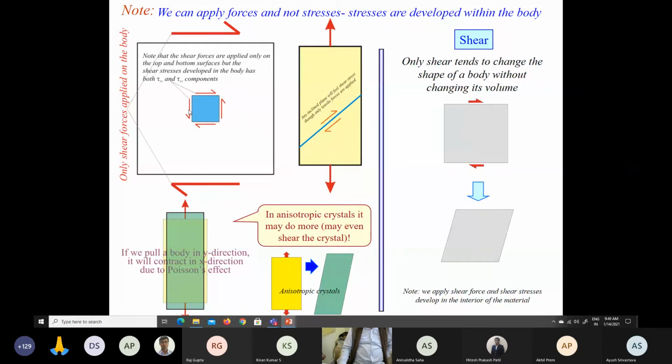the shear stresses will be in equilibrium. So if you take a moment about the center point of the stress element, and the center point can be found by joining the diagonals, the forces causing the moment should balance to keep it in equilibrium. Okay.